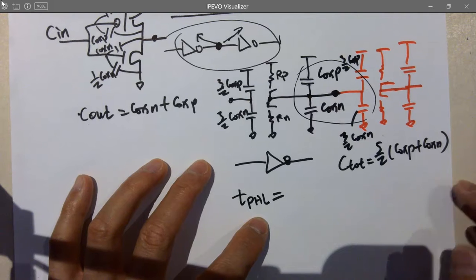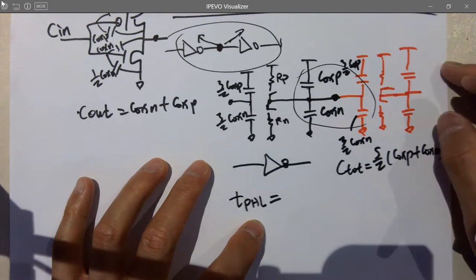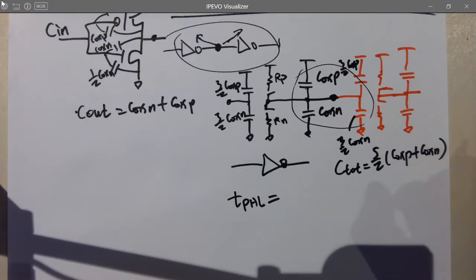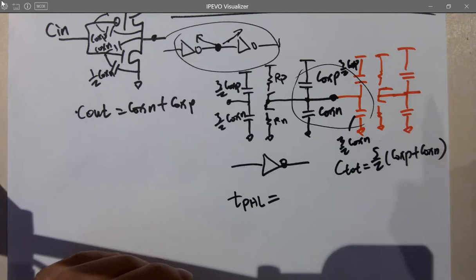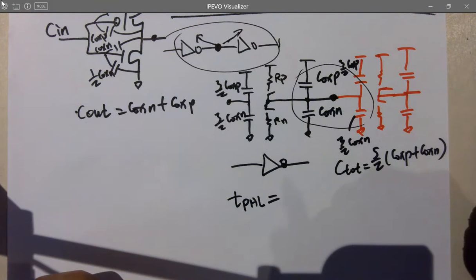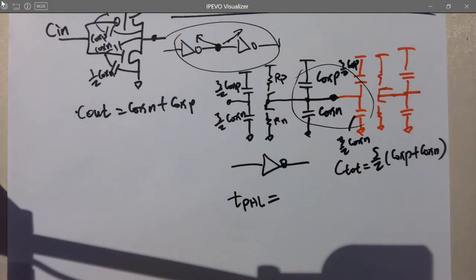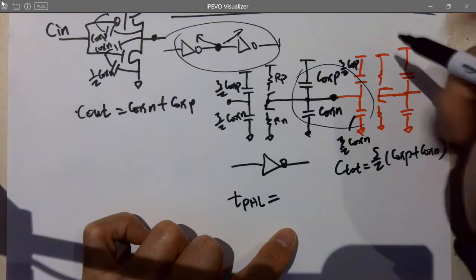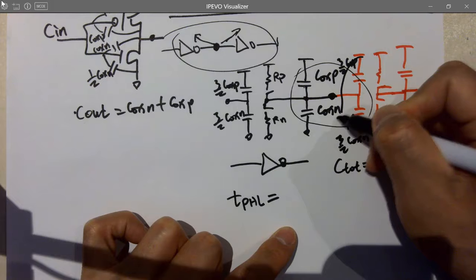Oh yeah, so that's where... So I had the same question when I was a student. Okay, so now what's the best theory to explain that? Whenever we are looking at a transient signal, it's like AC. We only analyze AC, but not DC. So when we do AC analysis, or just looking at the varying signals, all the DC sources are actually AC grounds. So these are considered to be grounded.